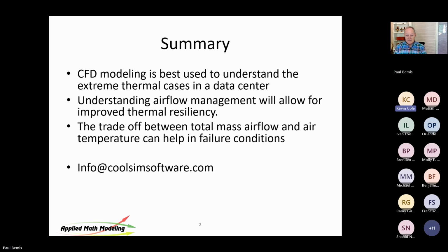Ramesh had a question about whether there's an ideal raised floor height, considering that there are some utilities below the floor. Let's say the vertical height of utilities does not exceed 6 inches. Okay, so the question is, is there an ideal height? No. I mean, the bigger the better. What's your budget for raised floor, right? So bigger the better. Typically, I find them today at least 24, 36 inches is not uncommon.